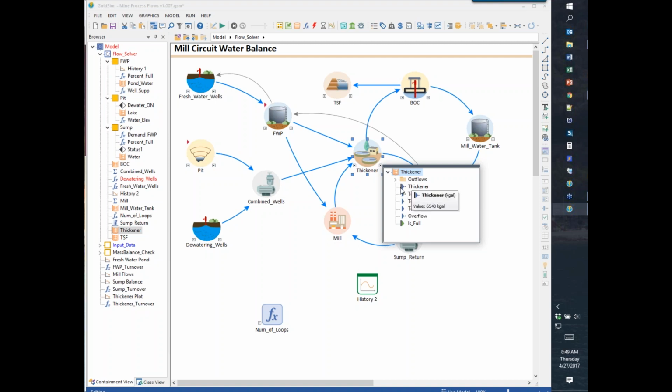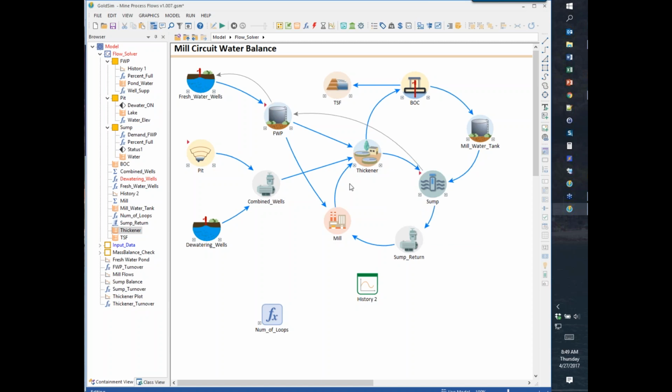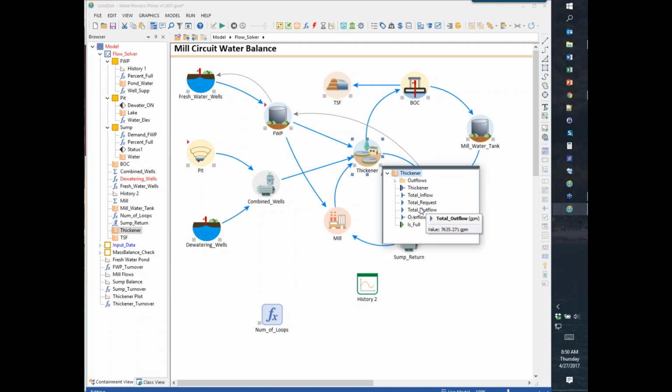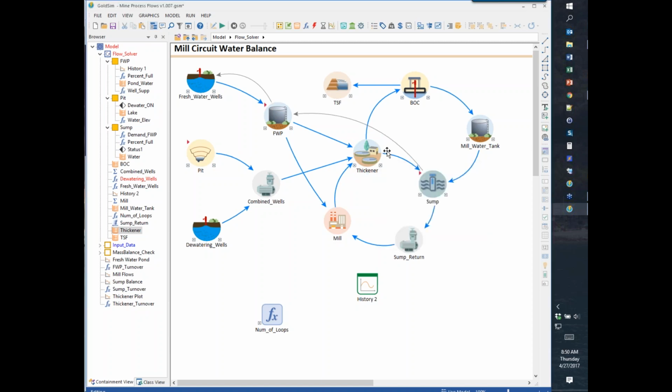Any output that has a black line next to it refers to a state variable, and when you refer to those kinds of outputs in a loop like this, you will not have a recursive loop error in your model. But as soon as you refer to one that is otherwise, then you will get a recursive loop error, and you'll have to put in a previous value, and that's why I have this here. But it doesn't matter, right? Because I'm looping the container, and so I don't get the delay, so it works out.